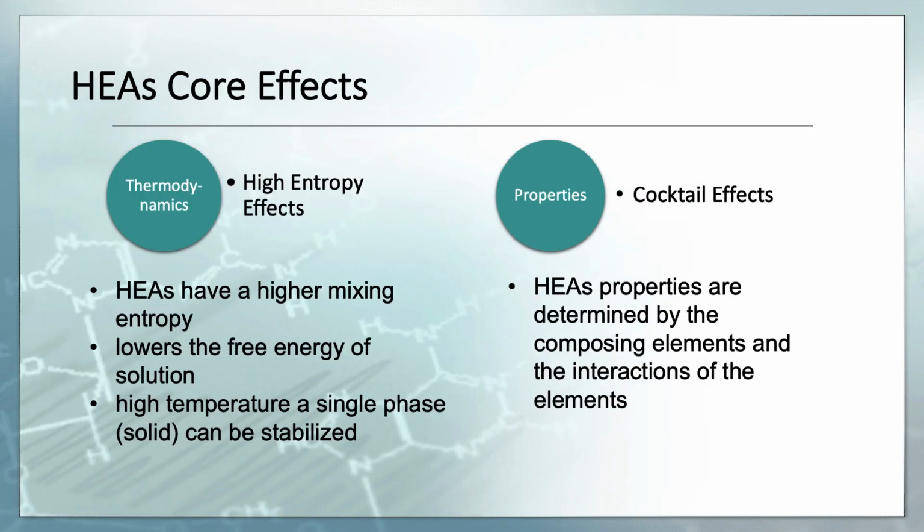The high entropy effect details that since HEAs have a higher mixing entropy, this causes the energy of the solution to lower at higher temperatures and causes a single solid phase to be stabilized.